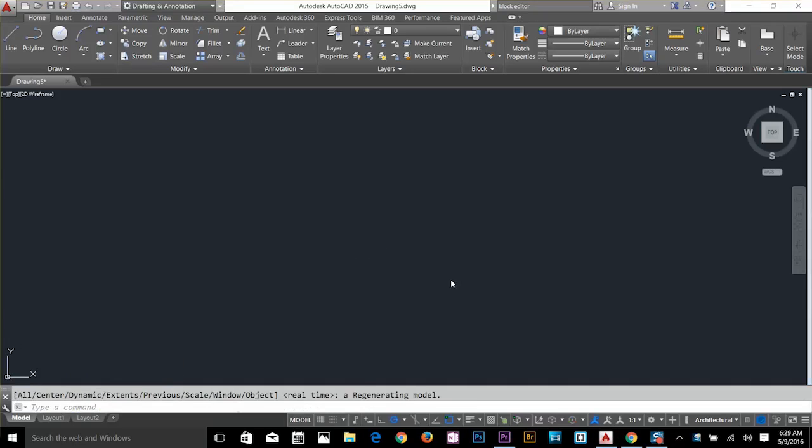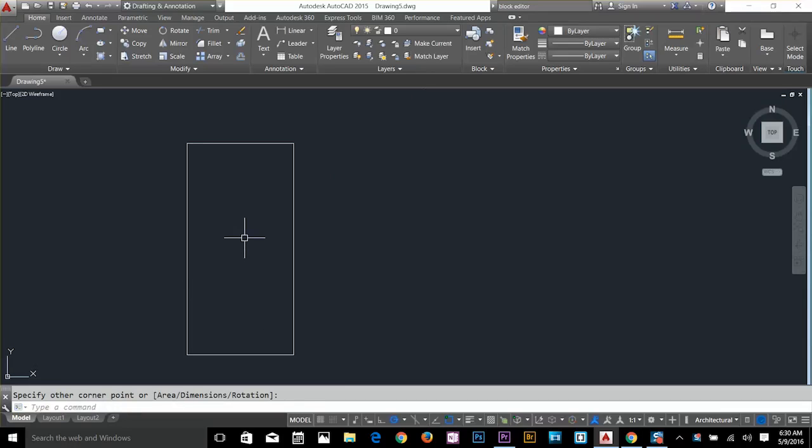Let's define an area of our house project. The area I've got is 42 feet by 85 feet. So I'm going to select a rectangle, click here, and click on dimension so you can define a dimension. I'm going to type 42 feet for my width, and length would be 85 feet. So I've got this rectangle, and this is the area I'll be working in.